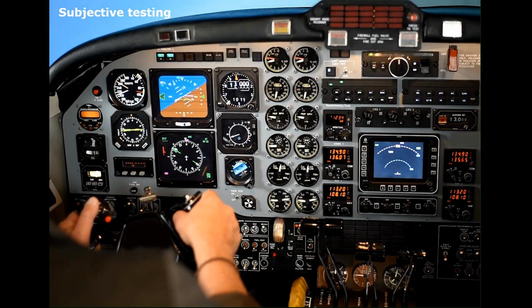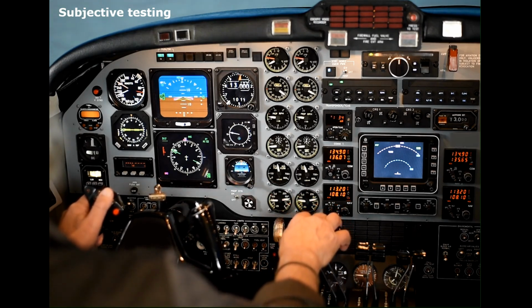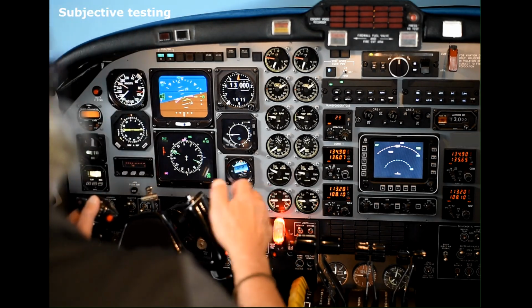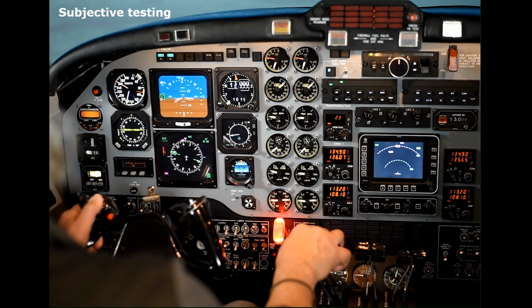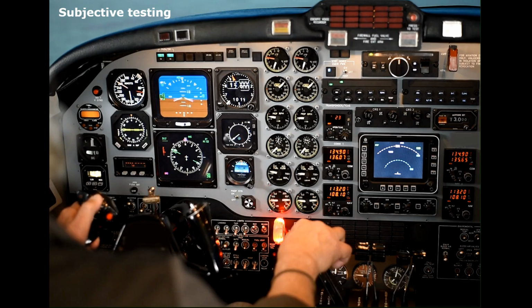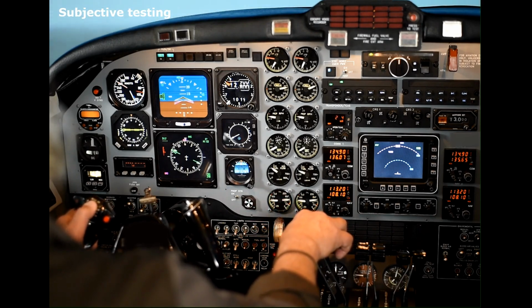Approaching heading. A little bit of push needed. Stay at 13,000. Now I'm reducing power. Gear warning. As the speed decreases, more trim needed. I'm reducing to 130 knots. More trim needed. 130 knots, almost in the trim.